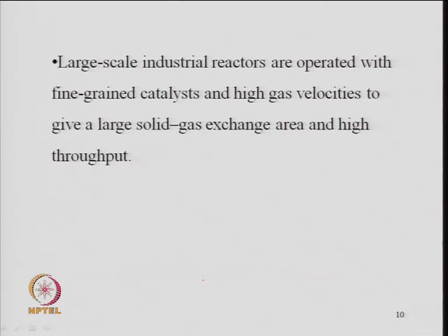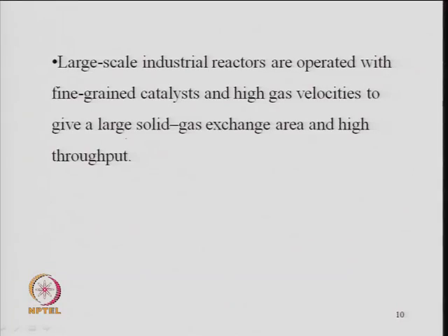So, if you look at the large scale industrial reactors, generally they are operated with fine grained catalyst and high gas velocity to give a large solid gas exchange in the reactor. So, that is again important when you look at the high throughput, that the large solid gas exchange area and high throughput. So, that is important.